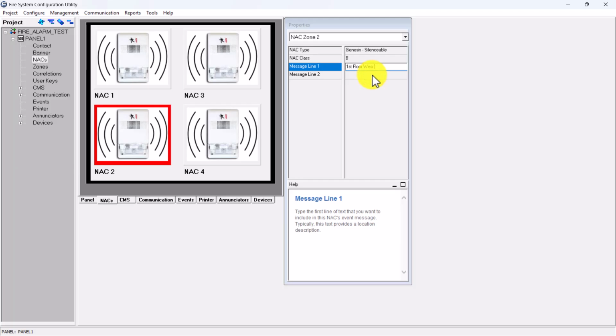So now when we download to the fire alarm control panel, the smoke detectors that are installed, these devices that are installed, will turn on the horns, all four of the horns and strobes. It will shut the fans down, the point types that need to, and it will also recall the elevator.